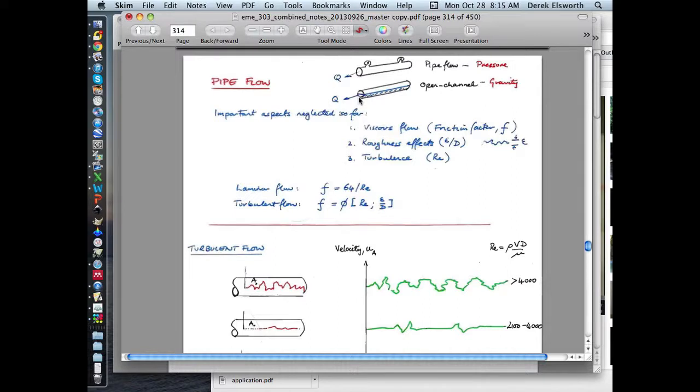And so pipe flow is true in both of these cases, but the property that will govern pipe flow in this case is that we'd want to get Reynolds number similitude, but we'd measure the behavior of this in terms of the Euler number. And in the half-filled pipe, we'd expect to get Reynolds number similitude, but actually it would be the Froude number which would control behavior.